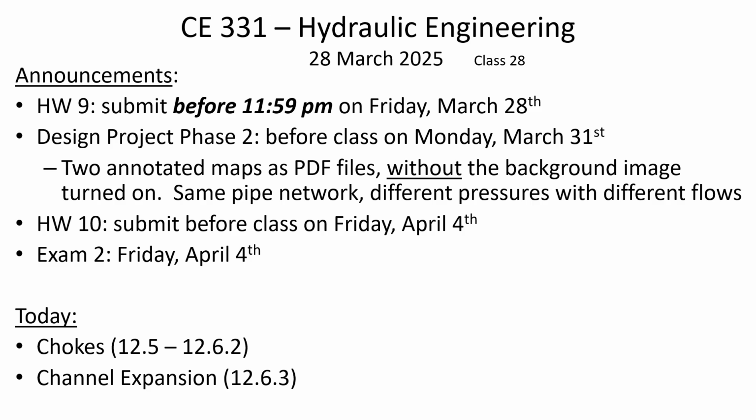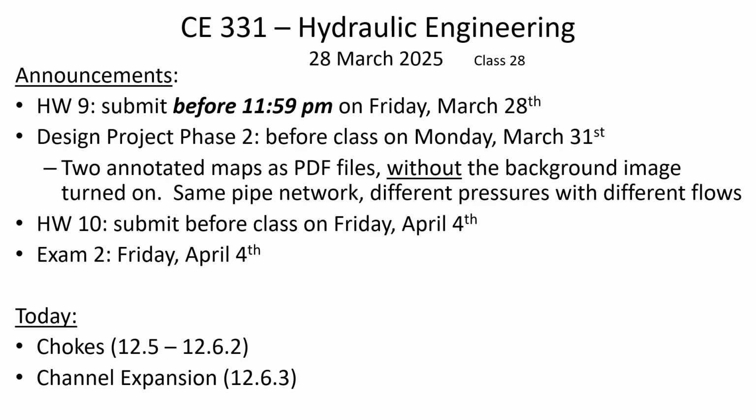Does anybody have any questions about these announcements or the schedule over the coming week? Yeah. For the zero flow rate, you just, on the junctions, do the outflow as zero? Yeah. You go back into the demand collection, and all the locations that you previously had defined your flow rate, you just go back in there and you zero it out.